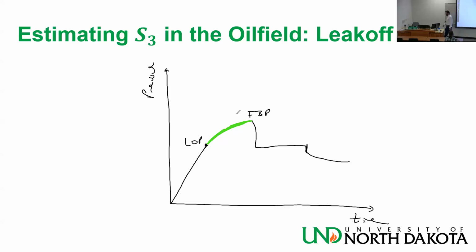So what I do in the oil field when I do leak-off testing is I pass the leak-off pressure. I don't want to get fracture initiation. I'm not yet doing a fracture. This is for a fracture. But if I do a leak-off test, I will stop pumping at some point. It will drop. I will get the ISIP and then the FCP.